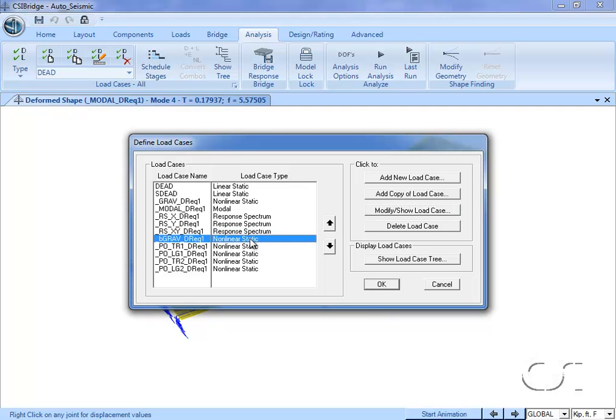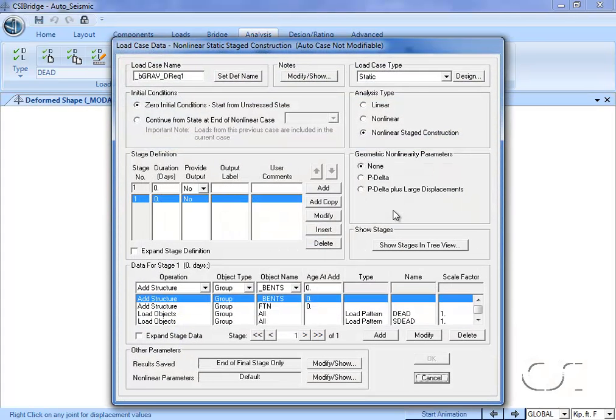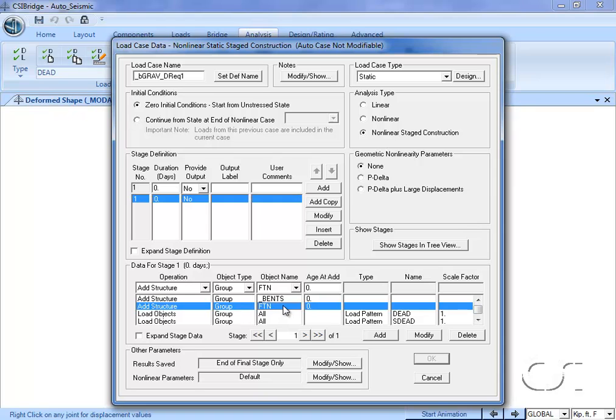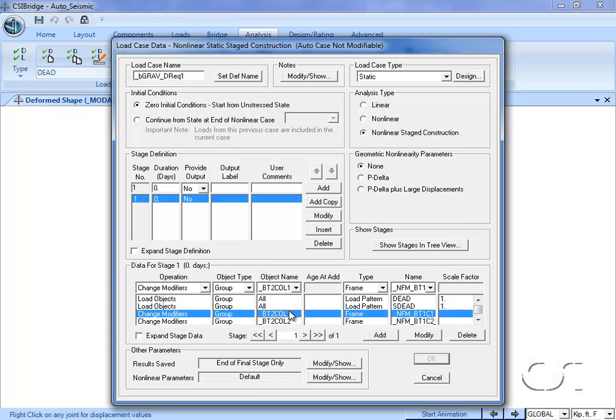The next case is associated with step 5 and again represents a deadload case, but this time consists of only the bents and foundation structure loaded with equivalent loads from the bridge deck. Again, cracked sections are used, and this step is needed because the structure is seismic design category D, which means a pushover of the bents is required.